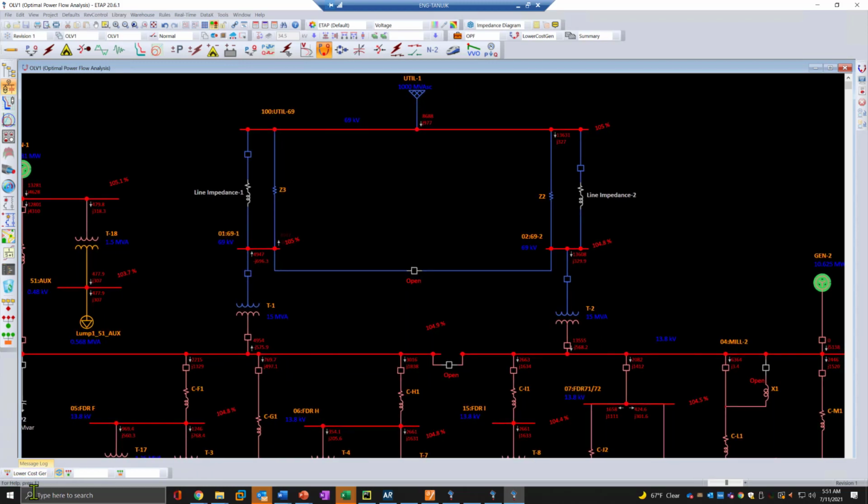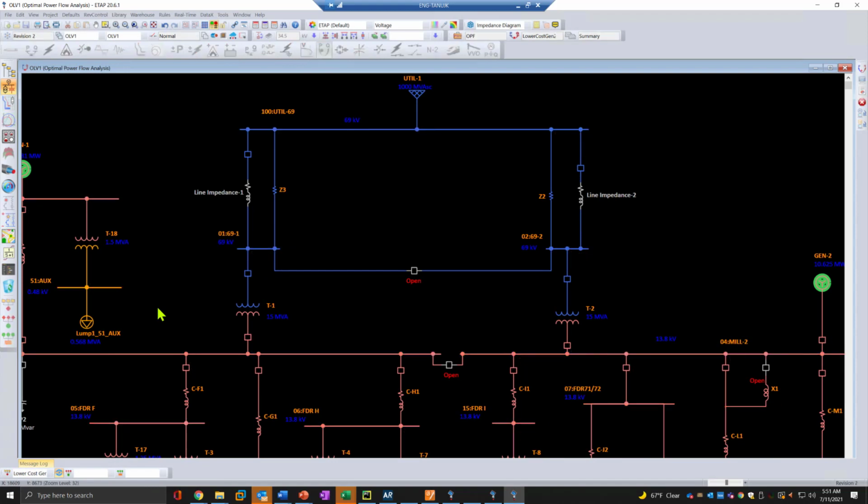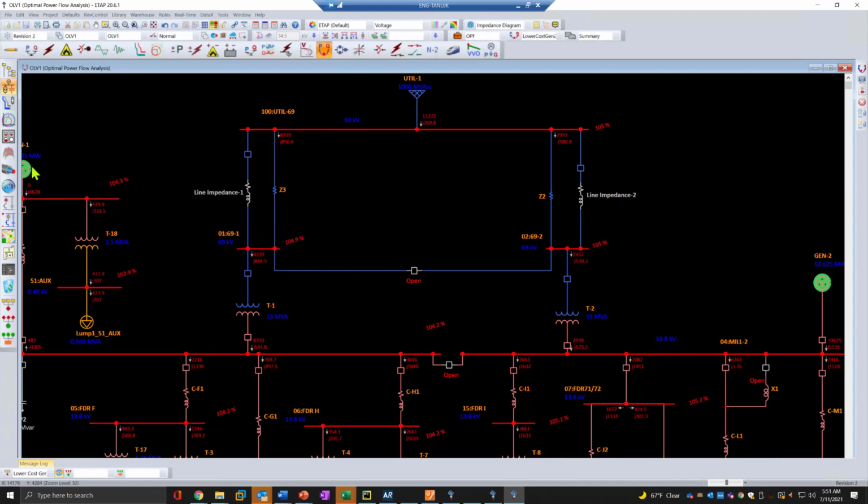Now when we switch over such that generator 2 now happens to be the cheapest source, you can see generator 1 megawatt going to 0 and generator 2 picking up almost 10 megawatt while the grid actually picks up 11.2. And this is a case where there's a blend between the energy price on the grid and the generator power. So they're not dispatched the same as generator 1.